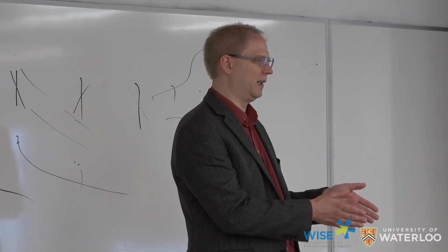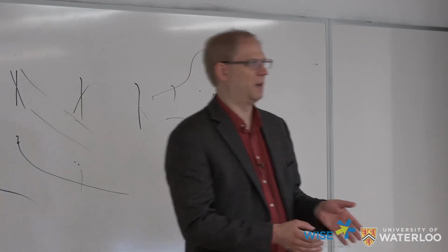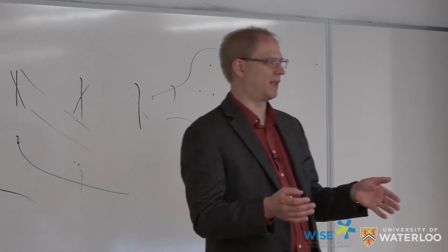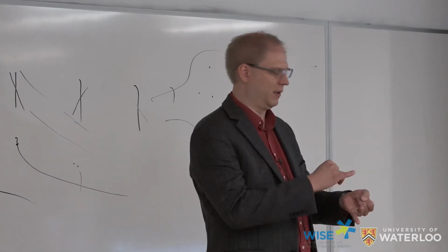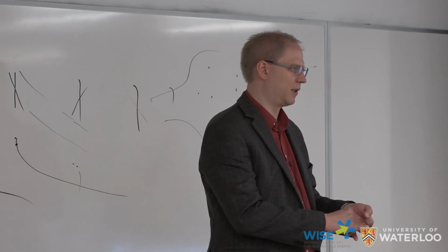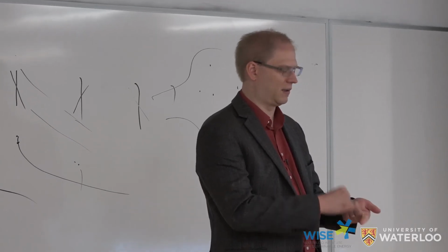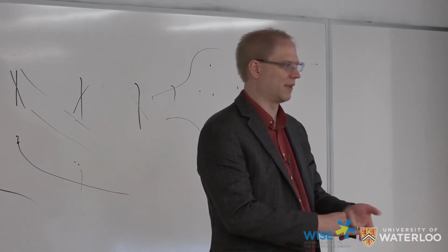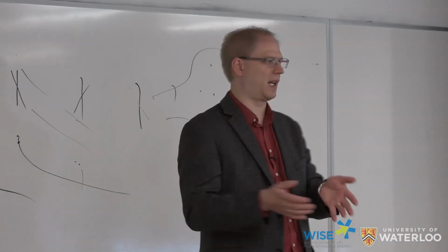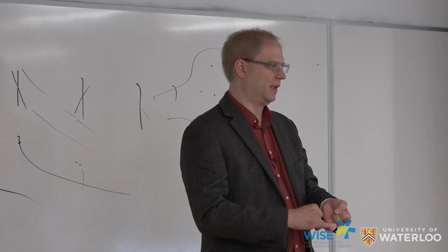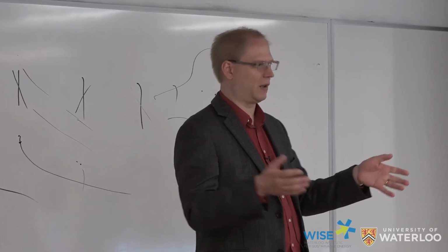What's the most important? And so what we're doing right now is effectively a sensitivity analysis to say what in the inflow, so shear, veer, turbulence intensity, length scale, coherence, Reynolds stresses, all the things that can go on in the inflow, what of those things actually matters to the things that I care about: ultimate loads, fatigue loads for operational turbines.